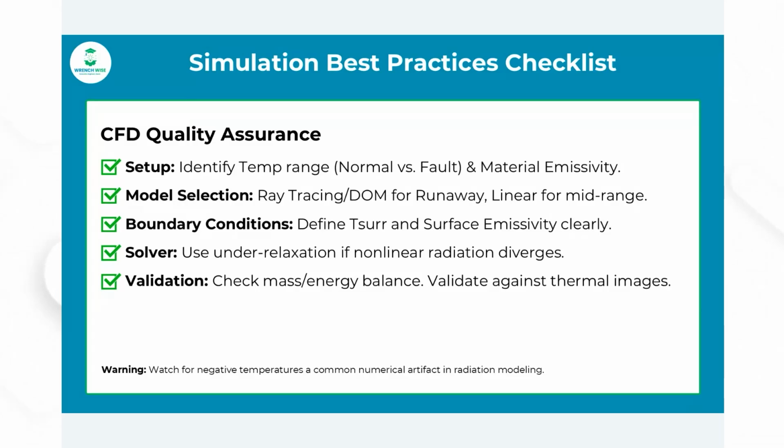This is a question that gets asked many times. How do you know you are right with validation? For thermal simulations, one of the biggest things you want to do is an energy balance, which is, does energy in minus energy out actually equal 0? If energy is disappearing somewhere, either your mesh or your absorption model is flawed. But for the most part, energy in, energy out, and checking your energy residuals, these are very important.